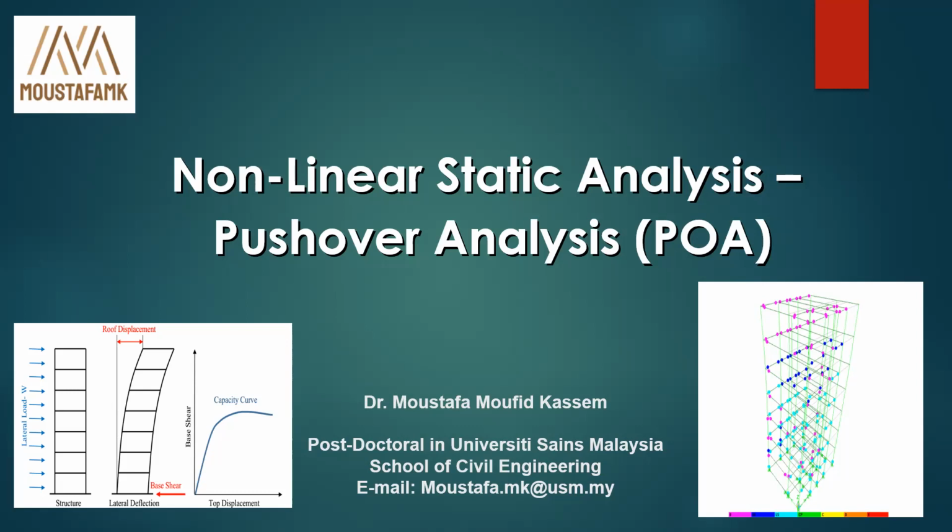The nonlinear dynamic method, like time history analysis, is a more complicated topic and requires more computing effort to model, because it requires supercomputers, ground motions, and a lot of intensity measures, damage measures, and engineering demand parameters.